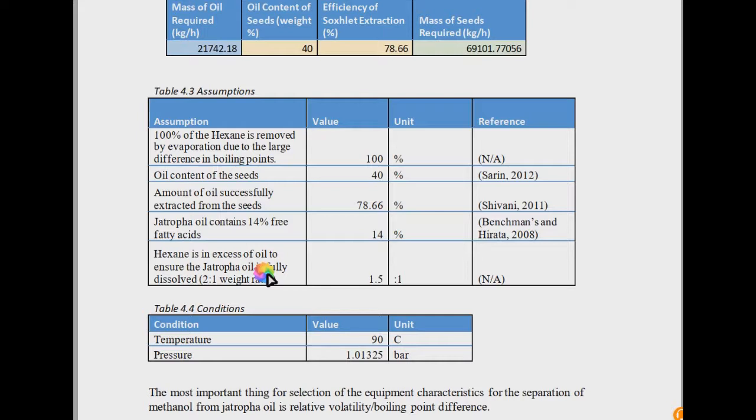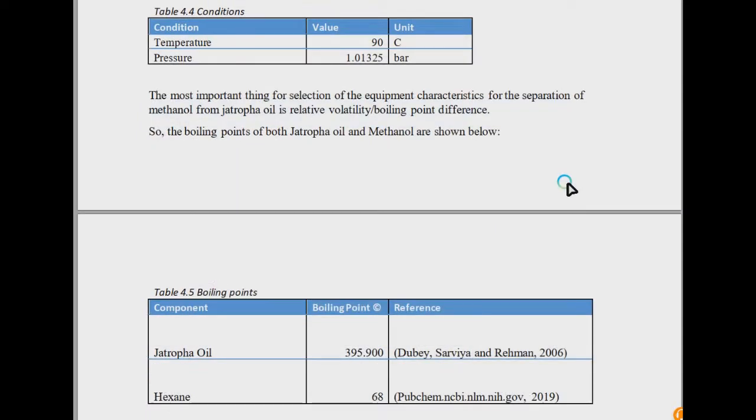But in solvent extraction, with a reasonable temperature, the solvent has the capacity to break the outer embryo coating of the seed, so the oil entrapped inside the membrane is extracted out. You will not always say the seed is porous. Actually, it is non-porous in most cases, because the coating is tough, like an eggshell coating.